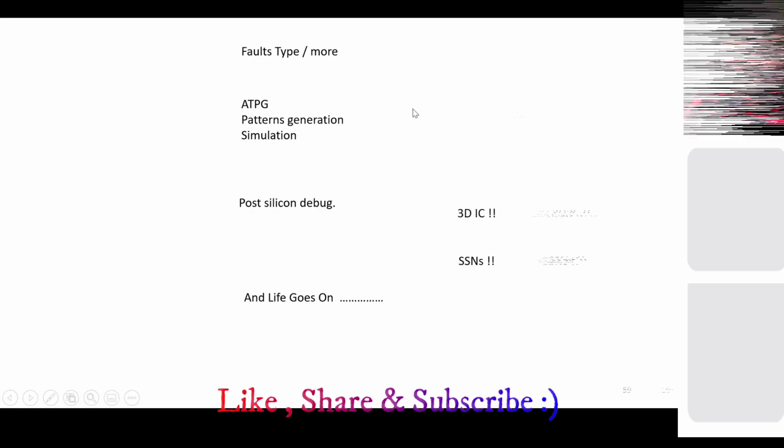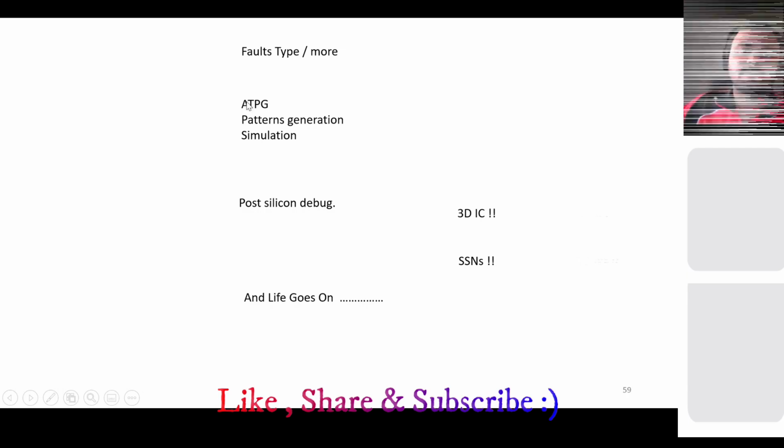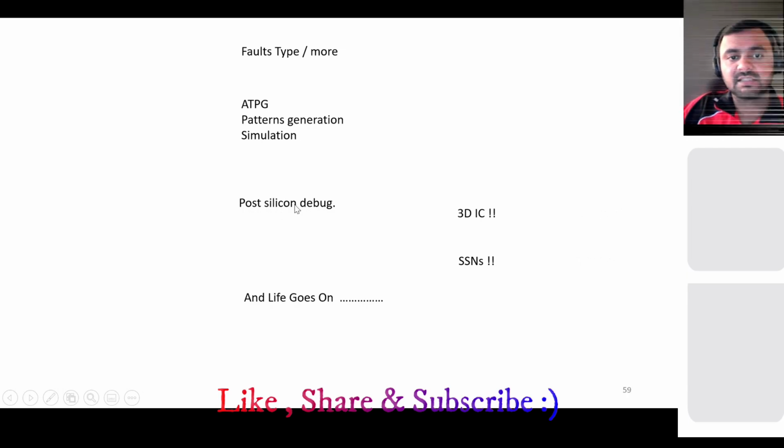Then pattern generation and simulation, we already discussed: we generate the patterns to detect those faults, and then simulate to see if we are able to detect all the faults or not. Even though everything passes, once the silicon is manufactured, you may get some defects, called manufacturing defects. So you do post-silicon debug and provide feedback to the test team about the fault we have found, and we need to redo it.